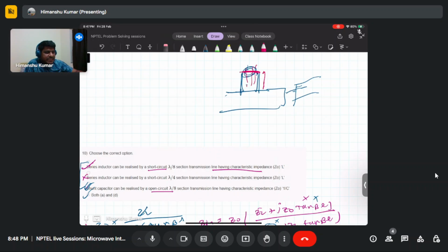Yeah, so basically you only need this impedance transformer and those lines, so shunt and series kind of topology. For those cases you need a different kind of combination. Suppose you want to match to a coaxial line, so you can't connect anything in shunt. Then the only option is a series line you connect. Coaxial cable, yeah.